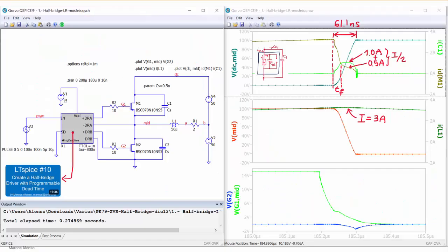And finally, we did a simulation in which we showed the different waveforms to demonstrate how we can make the increase of the voltage across the switch slow enough. So during the turning off process, during the process in which the current through the channel is decreasing, we are going to have in parallel very low voltage and therefore the losses are going to be also very small.